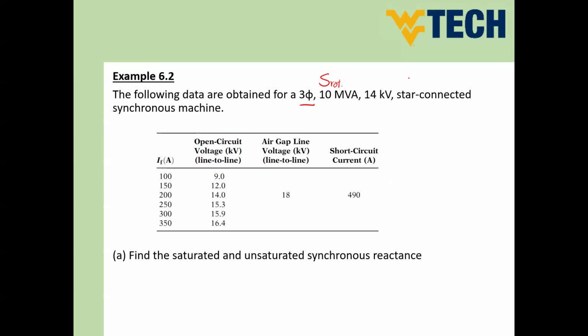Star means Y connected. So this means the 14 kilovolt is the terminal line-to-line value, star connected synchronous machine.